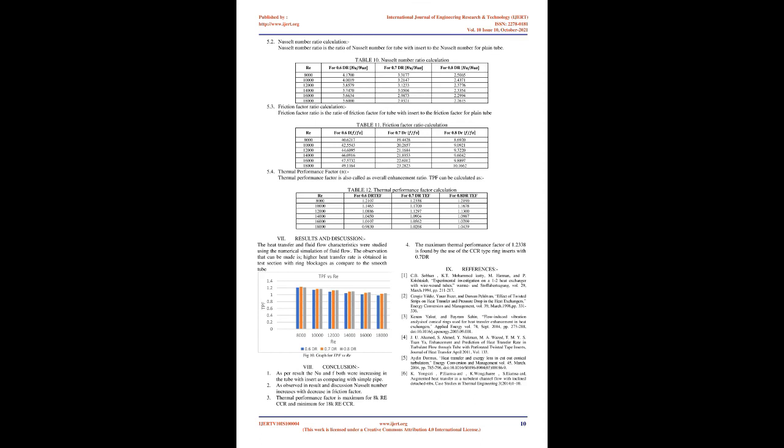2. Validation of simple pipe. For numerical analysis, selection of an appropriate model is required. By using the different ANSYS models, Nusselt number, Nu, and friction factor, f, were calculated and further compared with the empirical values of Nu and f. The standard deviation range is 20%.